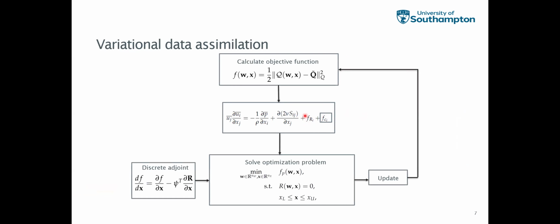Okay, I get it. So is it similar to a field inversion, but you just use the source term directly as a corrective field? That's correct. So in a field inversion case, you would find the scalar field, which is the multiplier to say the production term, right? You find the beta field, but in this case, you are finding a momentum or a vector field as opposed to a scalar field. Okay.